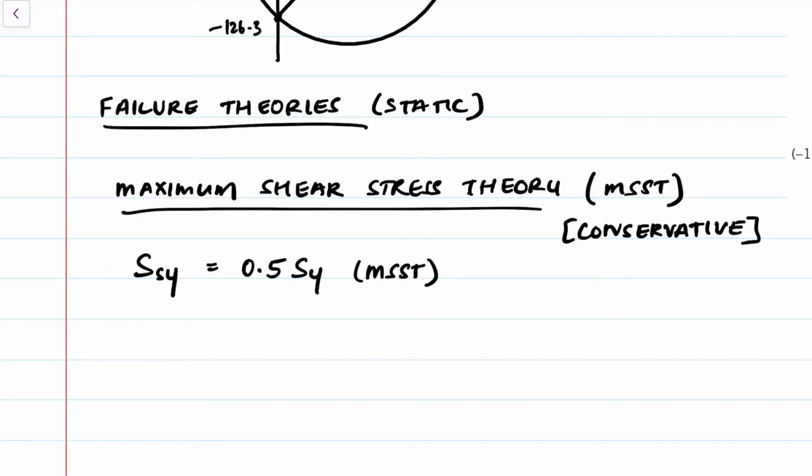And in our case, we have 1018 cold drawn steel. And this is from a different textbook. At the back of the appendix, you can pull out the value. But in our case, here, 1018 cold drawn, this is not available in your textbook. It is 370 megapascals. I think it's in appendix C in the textbook.